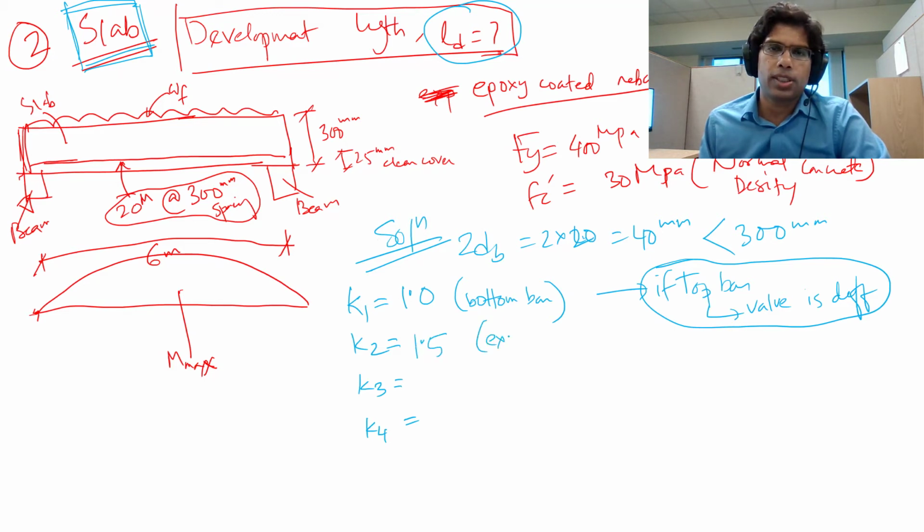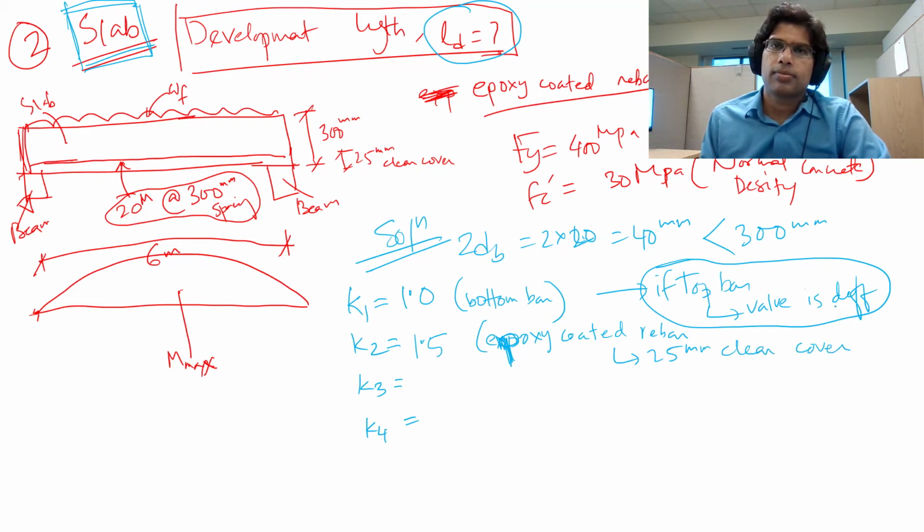Because we use epoxy coated rebar, and also we used a 25mm clear cover. Remember this 25mm clear cover from there to the bottom.